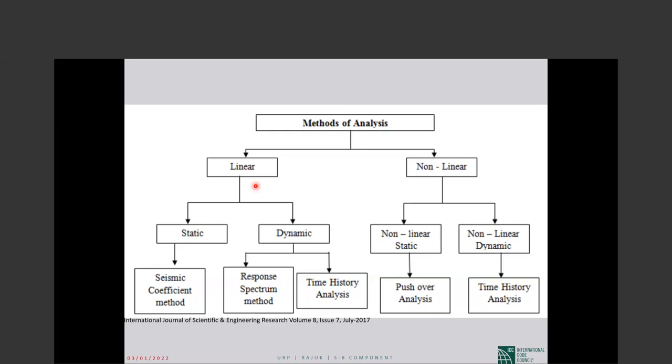So from the systematic evaluation point of view, each material, each different element of the building has two values, two strengths. One is the expected, the average, if you do tests, the average value, and one lower bound, average minus one standard deviation. So the material is the same, but the value that we use for the force control actions, for the scary ones, we use a smaller value for the strength of it.